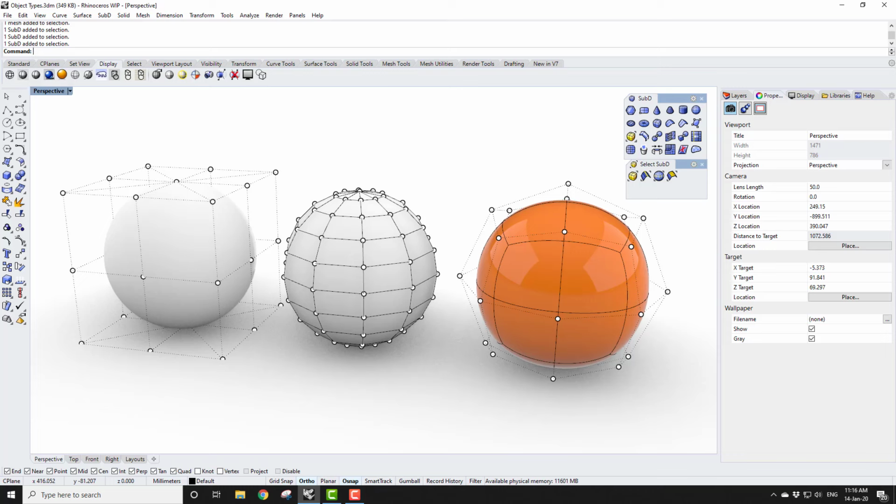The new SubD objects in Rhino are spline-based, so just as with Rhino NURBS objects, they provide a continuous description of curved geometry. This means that SubD geometry can be created accurately in Rhino, and this gets over one of the major criticisms of mesh-based SubD workflows that are often regarded as being approximate.